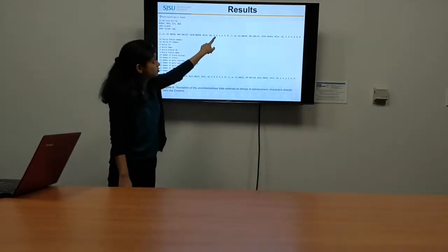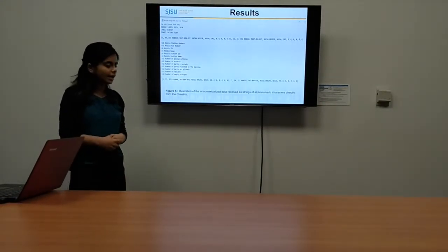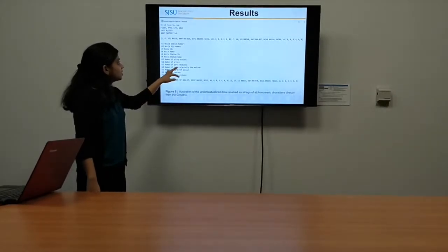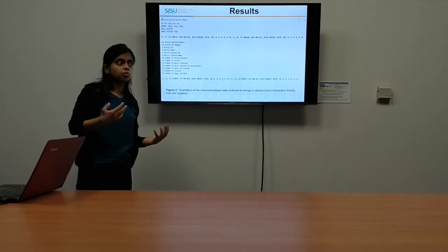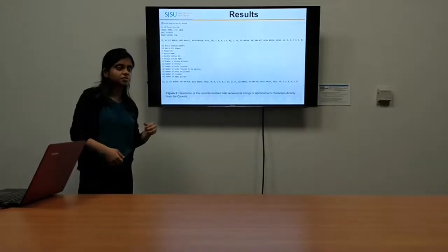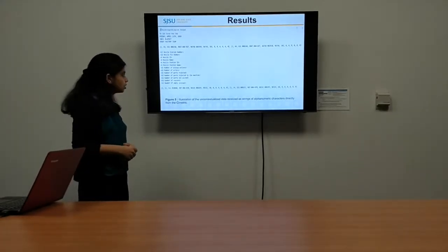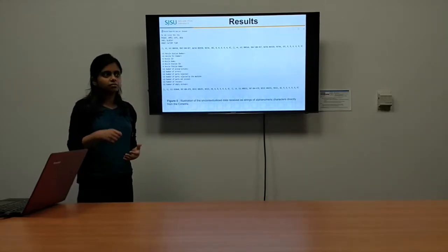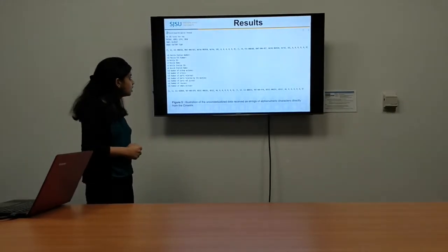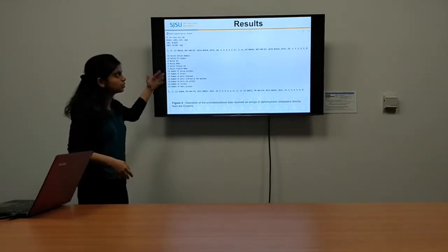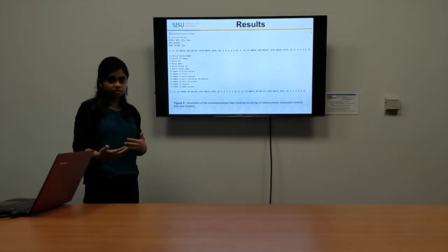Followed by the number of errors. For the first one, it was 0, which is great, but ideally it doesn't really happen that way. And then parts rejected by the machine. Parts rejected by the nozzle is one different thing. Parts rejected by machine is, did your machine stop during the production in between? And then parts not picked, again, did the nozzle miss picking up one part during the production? And rescans and empty pickups. Those are the kind of SEMI GEM compliant data that we particularly collected for the nozzle usage, as you can see from this diagram.